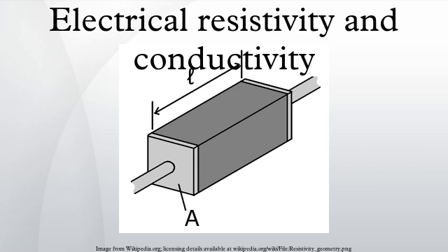General definition: the above definition was specific to resistors or conductors with a uniform cross-section, where current flows uniformly through them. A more basic and general definition starts from the fact that if there is an electric field inside a material, it will cause electric current to flow. The electrical resistivity rho is defined as the ratio of the electric field to the density of the current it creates: rho = E / J, where rho is the resistivity of the conductor material, E is the magnitude of the electric field, J is the magnitude of the current density, in which E and J are inside the conductor.